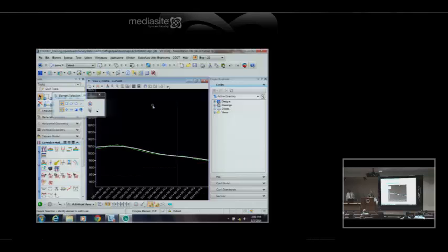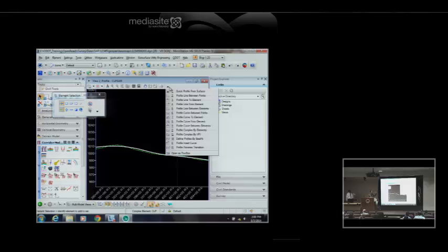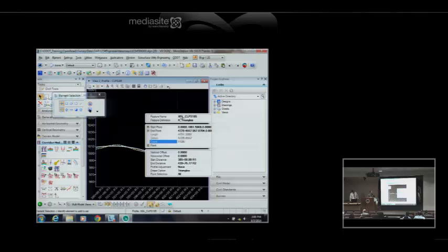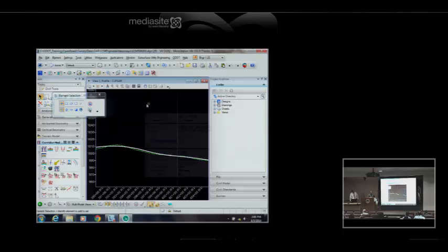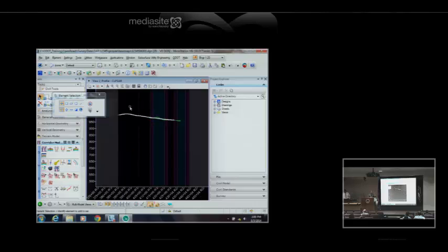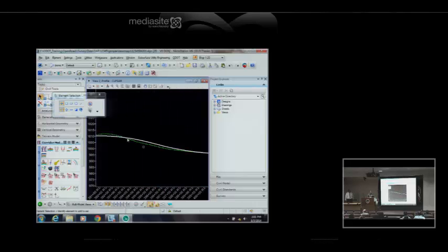And then there's a group of tools for laying out the vertical geometry. And then once I got that stuff defined, if I look at its properties, I've given it a name, and then I've exported that to the GPK. So it does reside in the GPK, and I'd have to plot it in a profile in a design file with Design Computation Manager in order to cut sheets. So at this point in the software, you can't cut sheets against this profile. It's not annotated with any slopes or anything. It's just kind of sitting out there in space.